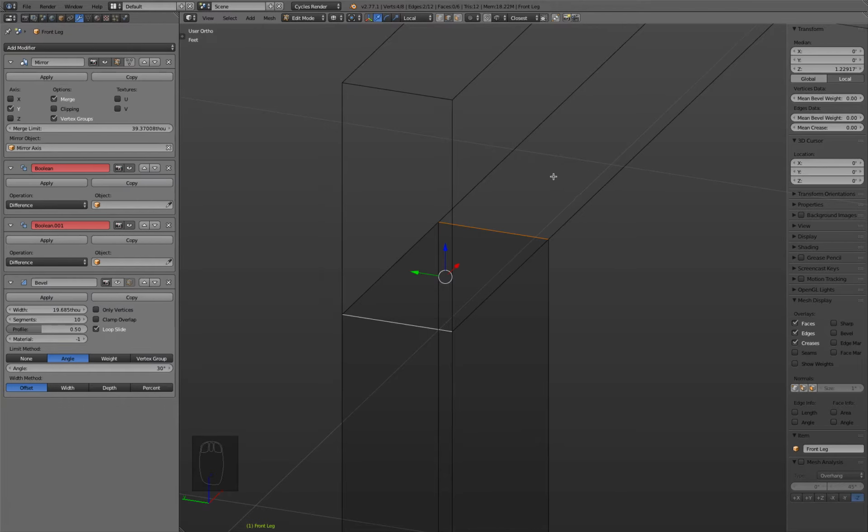And to do this, you can press K, and then you will see that the cursor will switch instantly to the shape of a knife. So when I go with the cursor, or with the knife icon, to an edge, you will see that the edge first will be highlighted in a yellow-greenish color, and then there's this green dot I can move around. So the green dot basically means where I start cutting into my geometry. Now I do not click the left mouse button, I'm in the K mode.